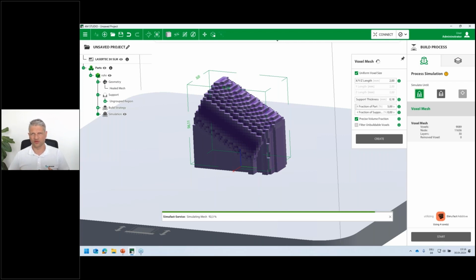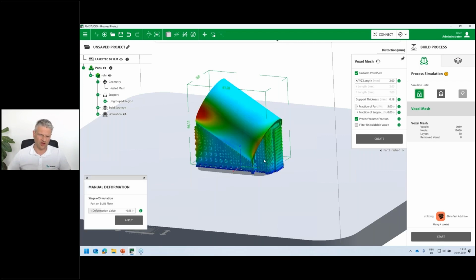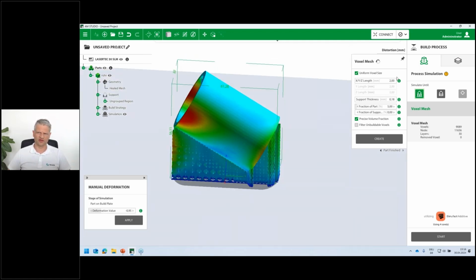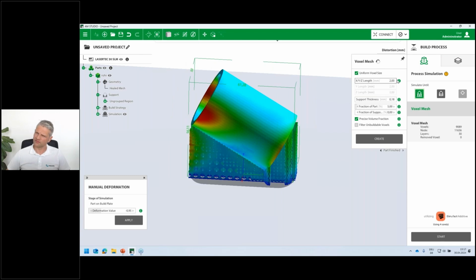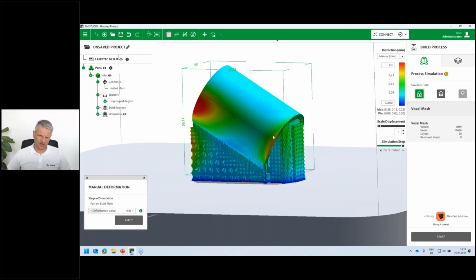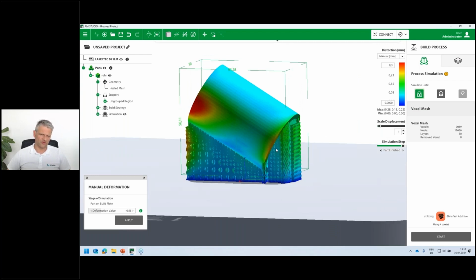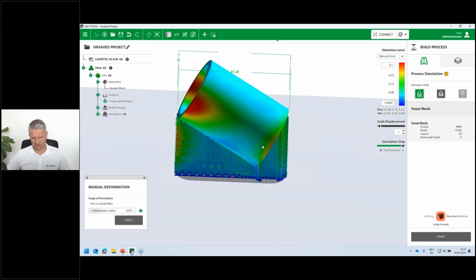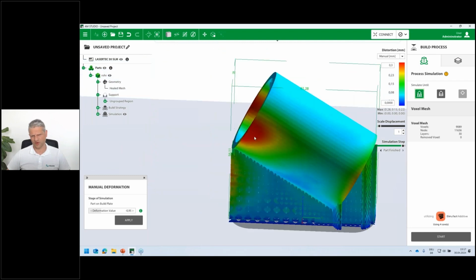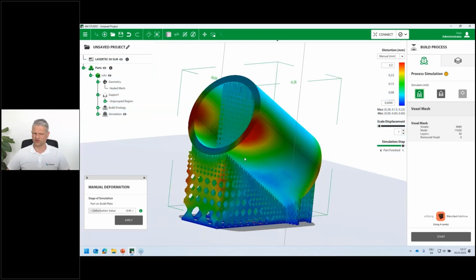This is sort of a sanity check. I want to find out if there are any critical areas, and for that I do not have to use a very small voxel size, because, as I mentioned beforehand, the simulation time will increase immensely when you decrease the voxel size. What you can see here now is that this big red area, which was visualized in the first simulation, has now gone back to a more orange one, but the hotspot here on the upper circle still remains.